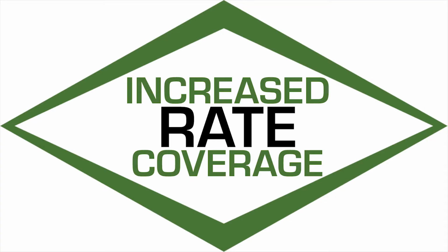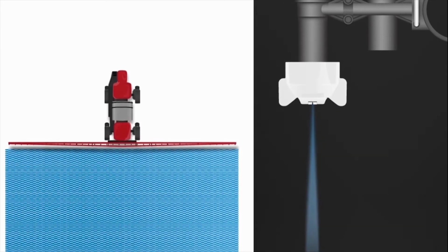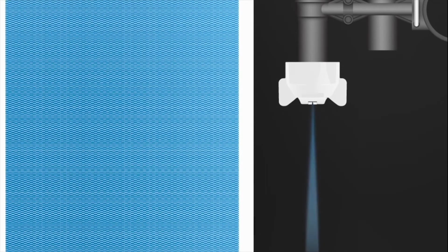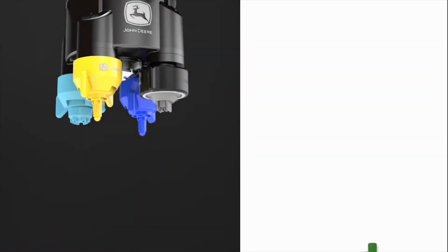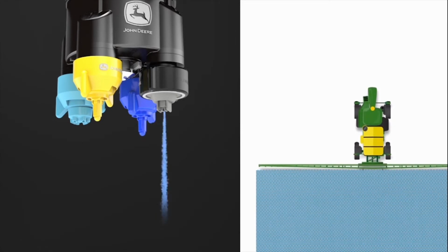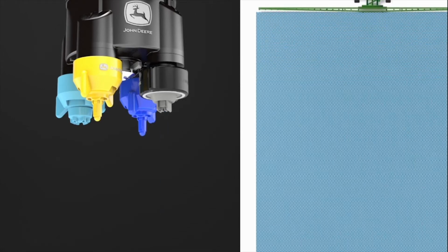In this video, first we look at our competitor system. This would be like an AIM Command Flex or a Capstan system pulsing at 10 times per second. If we take a closer look, when we compare the two systems, you'll see the difference. Now Deere, in this case, we're pulsing at 30 times a second. You'll notice a much tighter pattern in between on and off times of the individual nozzle. So you look at the checkerboarding on the left versus the much tighter pattern of the 30 hertz pulsing of the Deere system on the right-hand side.